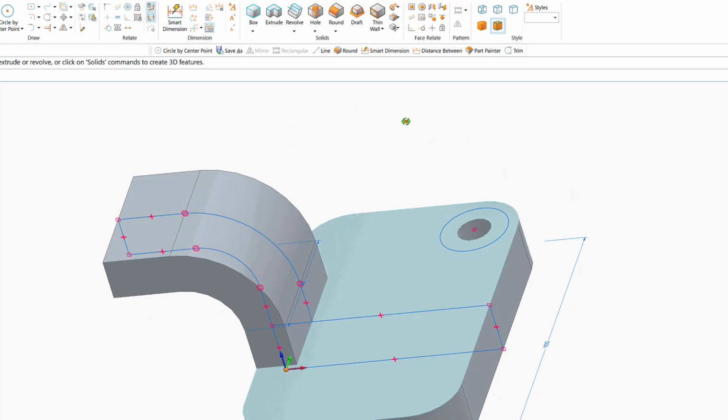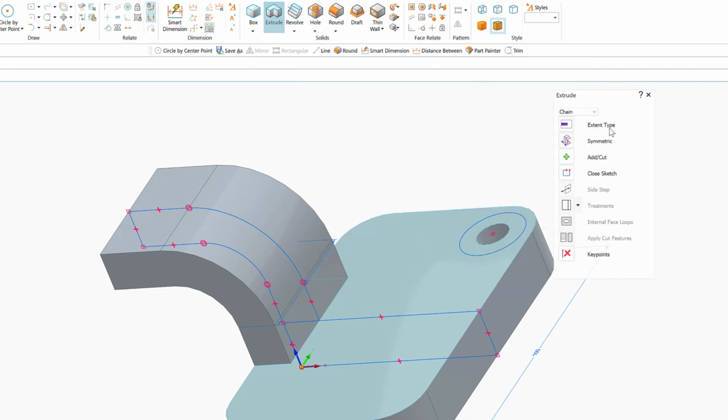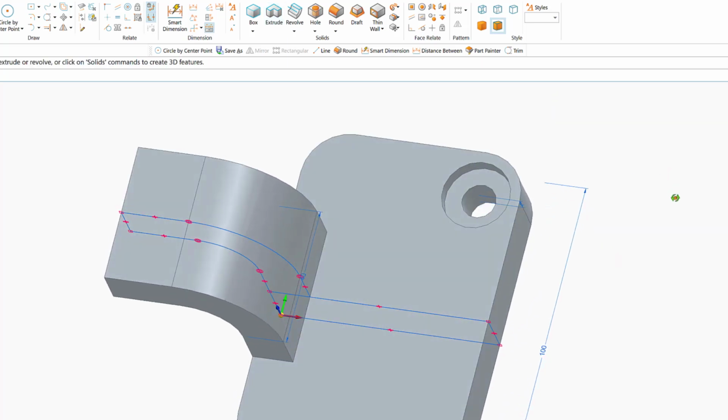The next step is, again, we're going to go down, so I'm going to extrude. I don't need this, I need the cut here. Then I'm going to click on the bigger circle, go down. I need to go down about 4 millimeters, so I'm going to put 4. Very good. I succeeded to make one of the holes.